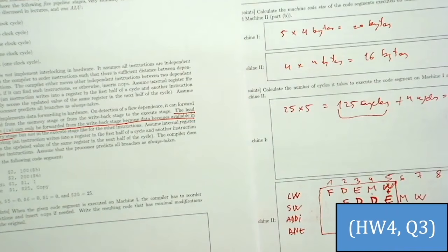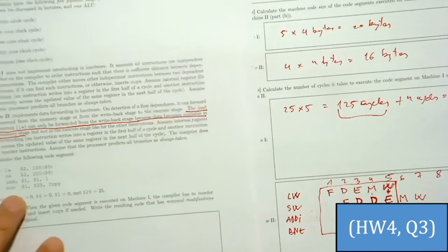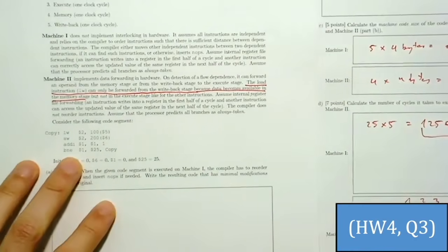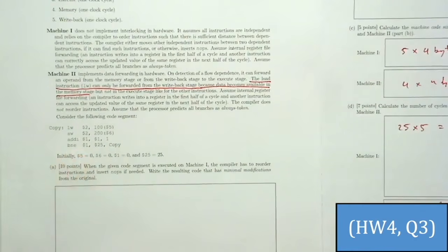It wouldn't work for me because I wouldn't have left decode stage because the valid bits aren't 1 yet. So there won't even be a situation where I get the data forwarded from memory to execute because I wouldn't be in execute stage yet because the valid bits aren't set yet. You see my problem? It works in the book. It has a hazard detection unit or what it's called. Then it works, but with scoreboarding, for me it doesn't.